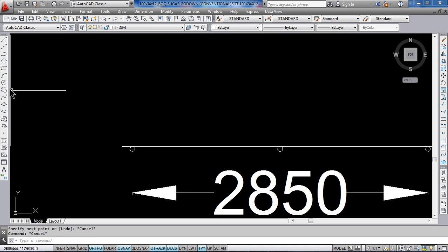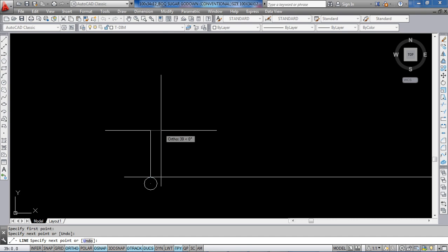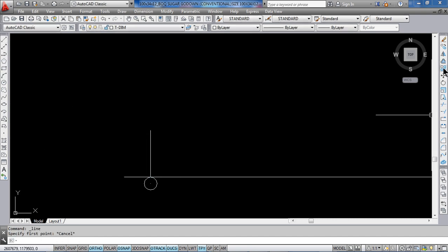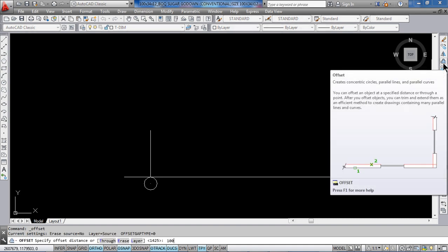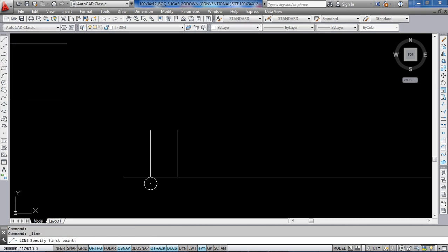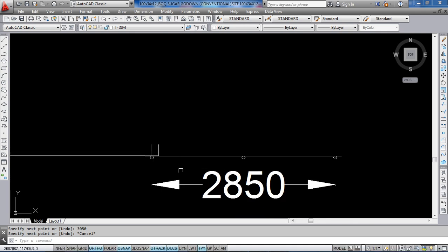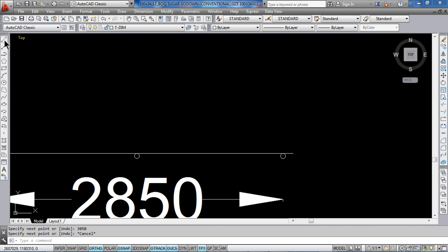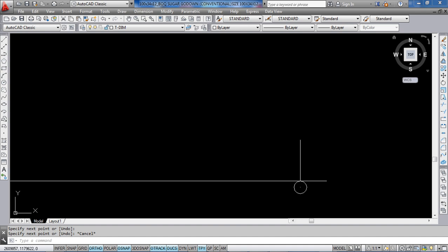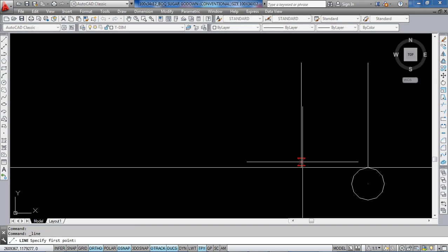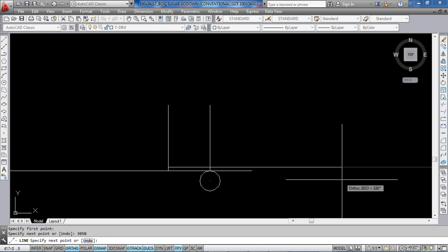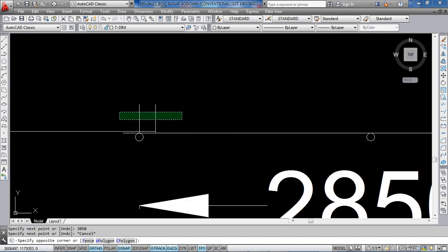So when we put the next sheet here, from here, by overlapping this 100 mm here, it will also be 3050. Similarly here, we will put a sheet by overlapping this 100 mm, like this, 3050. So this overlap is 200 mm.